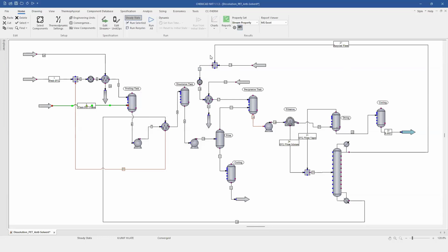For the water, we started the process without the recycles. Usually when you have recycles, you start your process with probably a dummy stream, an estimation of how much water will be added to the process. In this case, we added a ratio of 1:1 of water in comparison with the GVL into the system.